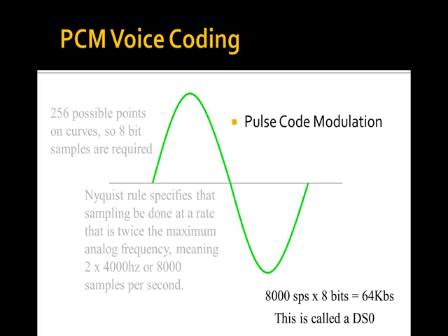Back at the beginning of the semester, we talked about the characteristics of telephone analog audio. And what we came up with is that we had to pass 300 hertz, 300 cycles a second, which is a fairly low tone in your voice. I can probably force my voice down to 300 hertz if I really try. Through 3,300 hertz, which is pretty high. It's not the very highest that the human voice can make, but it's way on up there. Almost all of the intelligence, the absolutely mandatory audio, is in that range. Now, the stuff that makes it sound pleasing for music and things like that is outside that range. But we can pass the information in the spoken word in that range of 300 to 3,300, which, if you do the math, is a bandwidth of 3 kilohertz.